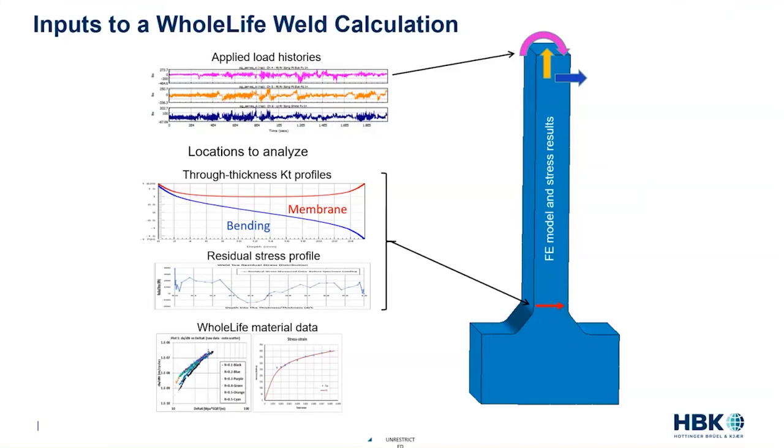crack was there. You'll see that we have two loading modes here. And again, this follows back to the things that we were doing with Seamweld, in that we need to understand what causes these peak stresses, because they have a different influence on fatigue. So we basically separate these into two different loading modes, bending and membrane. They're independent of how many load cases I bring in. I can go in and have multiple load cases, and automatically DesignLife will basically consolidate them into these two behaviors, membrane and bending.